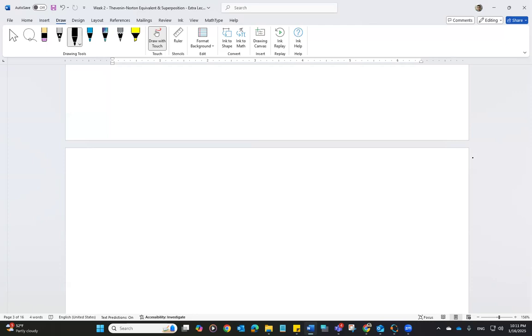So you can find the contribution because of that source. And the total contribution, of course, is going to be the sum of all the contributions that you have found by eliminating each source one by one, or eliminating all sources and keeping one source alive in the circuit.